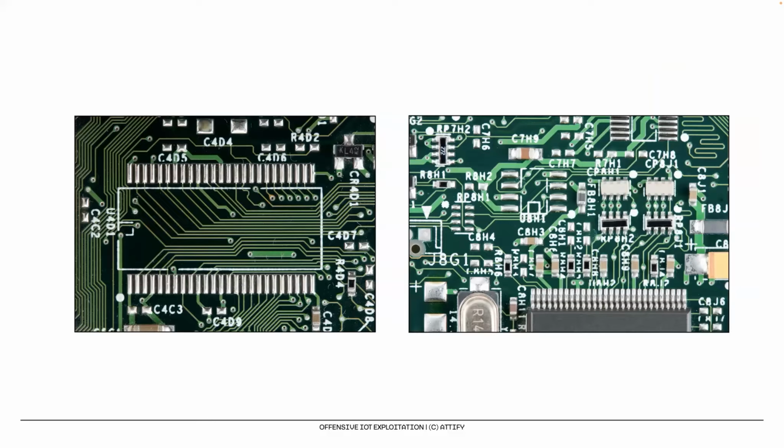And these tracks just act as a way of connection between two different components. Occasionally, one of the security protections that some vendors do is they slightly cut off the track if they have to break, let's say, the JTAG connection. So by looking at the JTAG pin for the SoC and where it's going, what is the exposed endpoint, and if you see that there's a track that's cut, that means that the vendor is trying to disable JTAG connection.